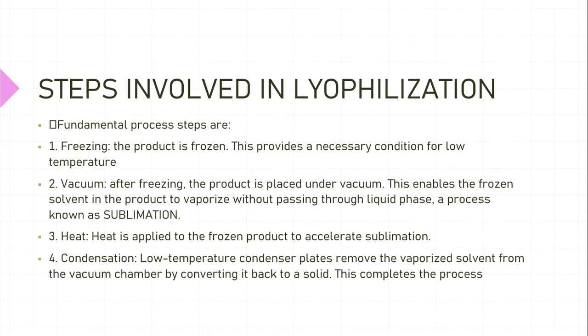This enables the frozen solvent in the product to vaporize without passing through the liquid phase. The product is already frozen, and when you apply lower pressure, vacuum, the vapors inside the compound vaporize without passing to a liquid phase, a process known as sublimation.